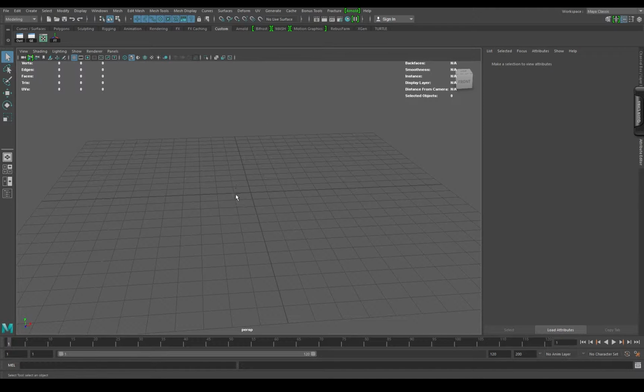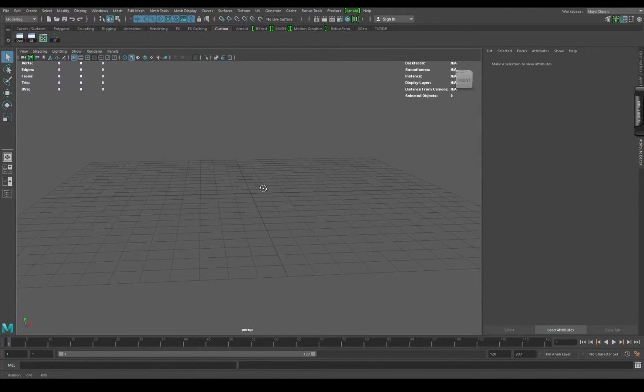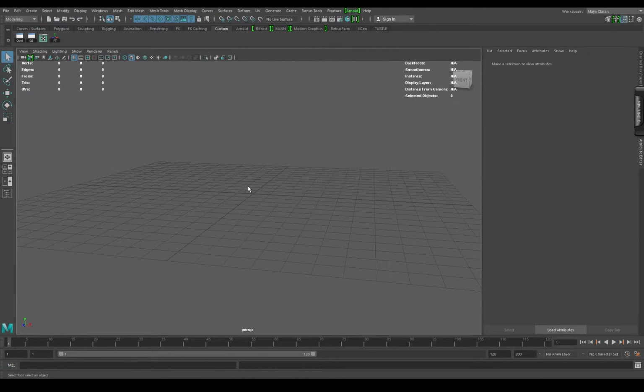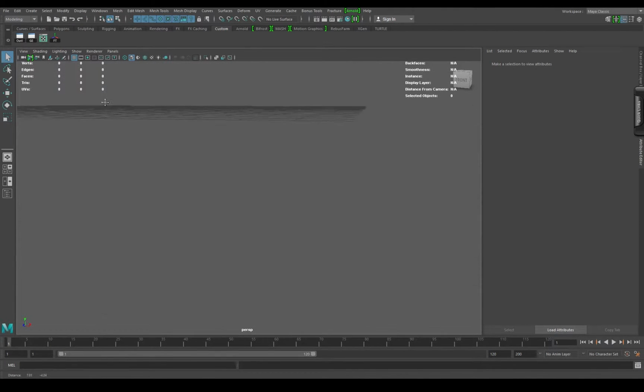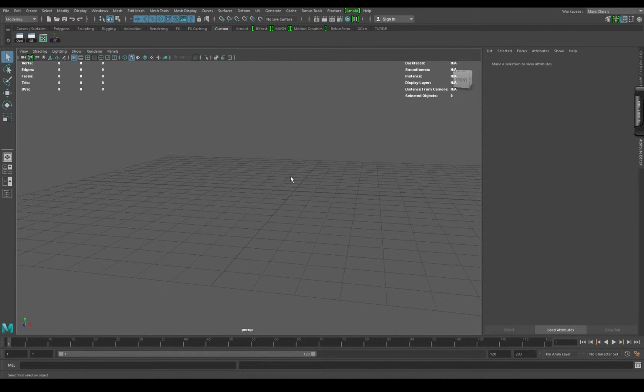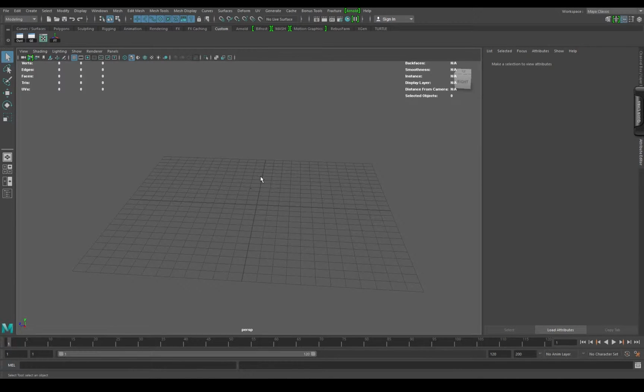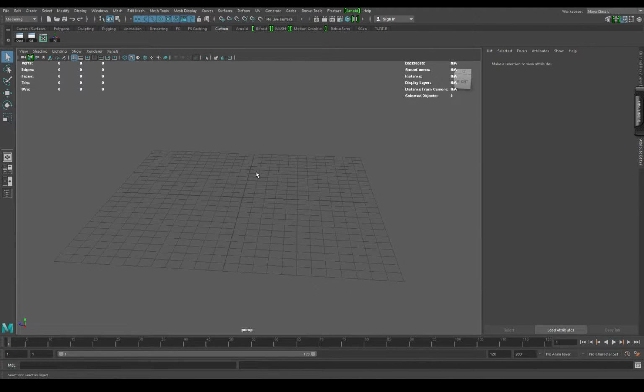Okay, so let's begin. If I hold down Alt and I hold my left mouse button down, I can rotate. If I hold down Alt and use my right mouse button, I can zoom in and out. Or if I hold down Alt and press in my middle, this wheel thingy, and click it down, I can pan. And I can also zoom by not holding Alt and just zooming in and out with my wheel. So Alt, left mouse button, rotate; Alt, middle mouse button, which is the wheel, pan; and Alt and right mouse button, zoom, or I can zoom just by scrolling my mouse wheel.